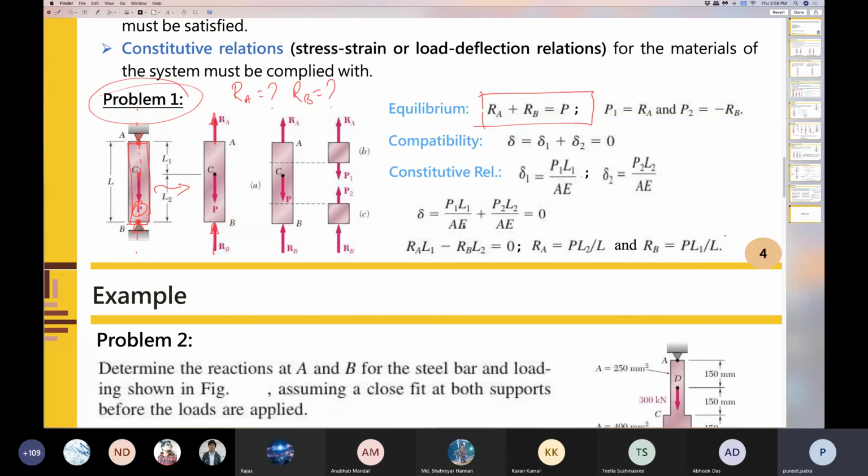I take the help of my knowledge of deflection, and I take the help that there is going to be no net displacement of this bar AB. That is because since this bar AB is connected to two hinges at A and B, it cannot really move, right? It cannot really show any kind of displacement. Joint B cannot show any displacement with respect to joint A. In other words, the net deflection of joint B is going to be equal to 0.